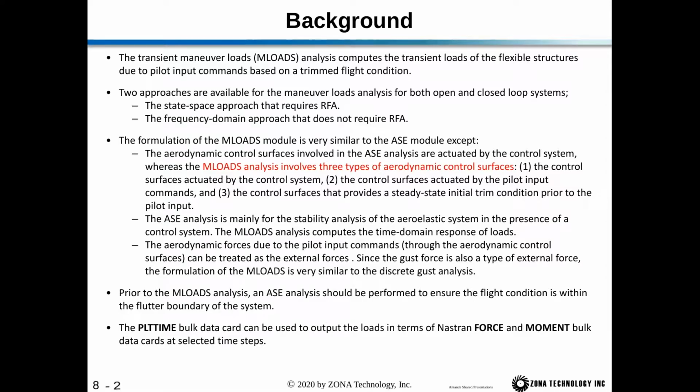loop systems. The first is the state space approach, which requires the rational function approximation, and the second is the frequency domain approach, which does not require the RFA. Now the formulation of the maneuver loads module is very similar to the ASE module, except the aerodynamic control surfaces involved in the ASE analysis are now actuated by the control system, whereas the MLOADS analysis has three types of aerodynamic control surfaces. One, we have the control surfaces actuated by the control system.